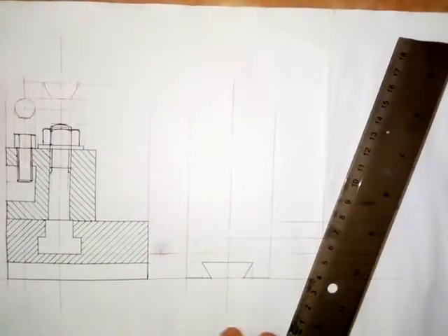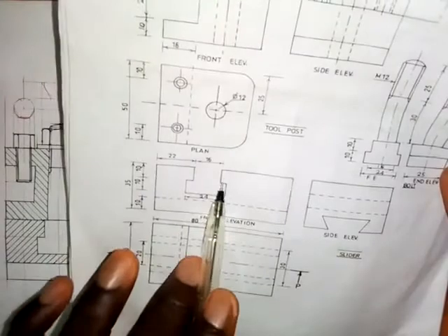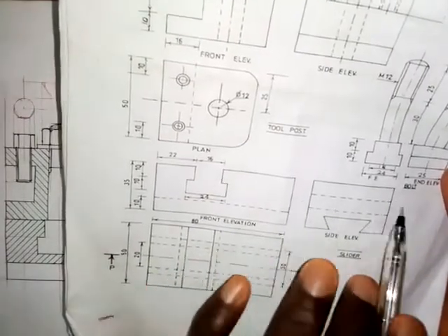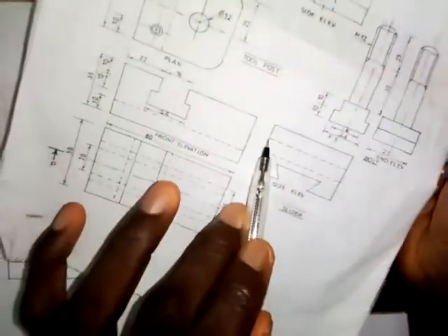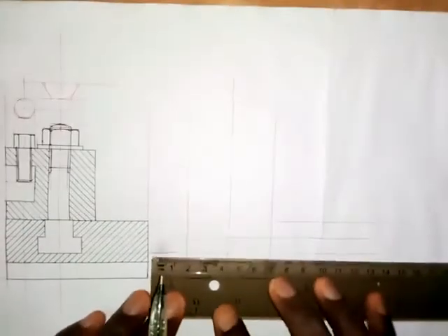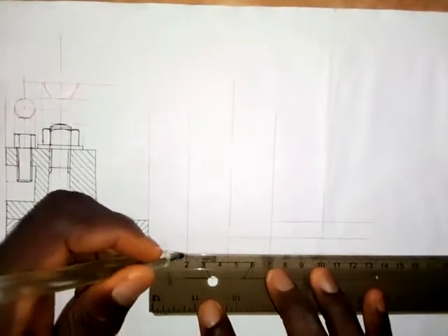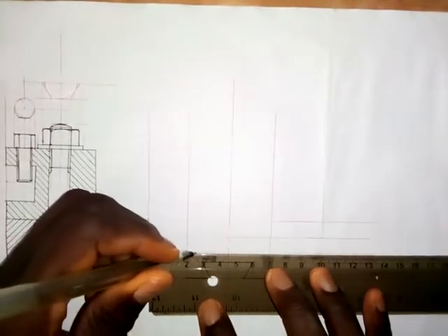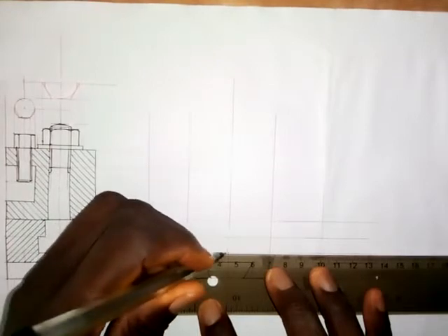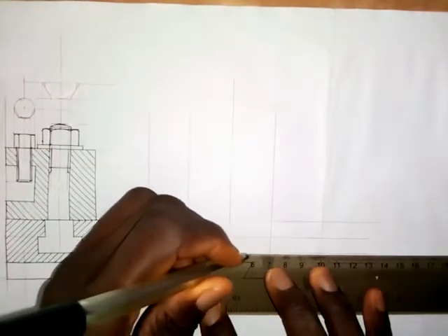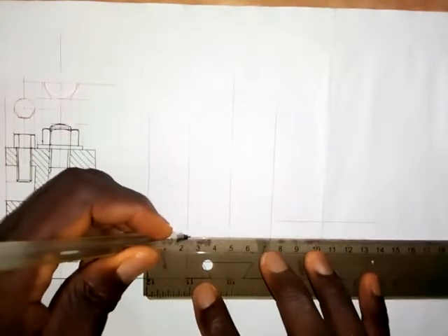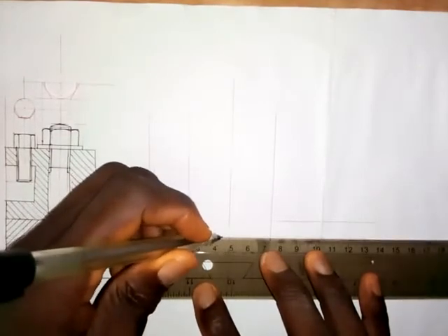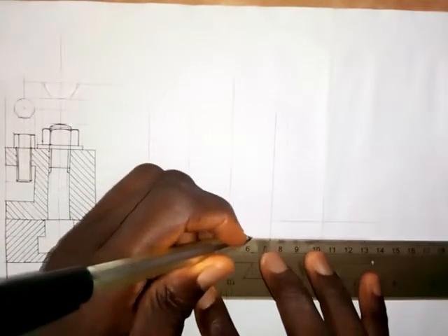Alright, so the next thing I'm going to have here, so here we have what? We have this shape that's here. So we have it here. We have it here. So it goes straight from the beginning to the end. So I'll just put it there as a short dashed line. That's how we're going to see it. We're going to see it like this in the end elevation or side elevation. This is how it will look. So it doesn't change, it will remain like this because it is hidden. When we are looking at it in that direction, it is hidden from us, so we are going to leave it hidden.